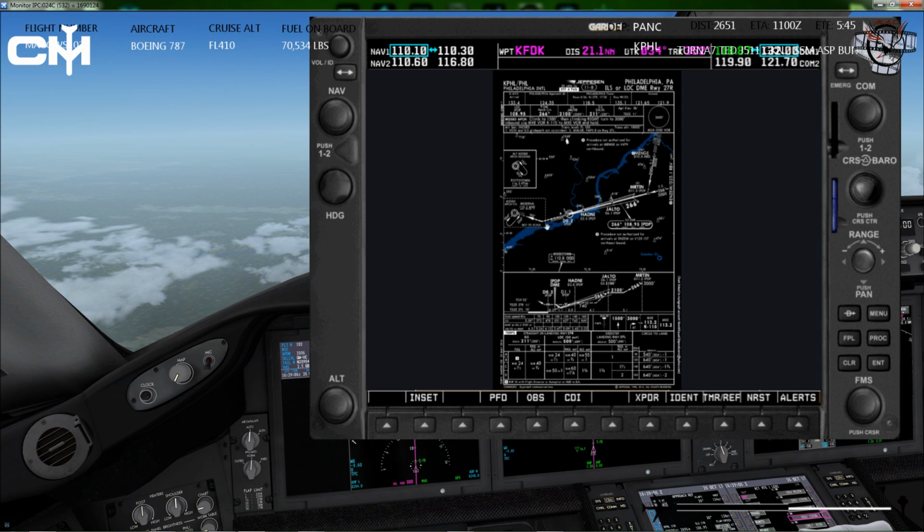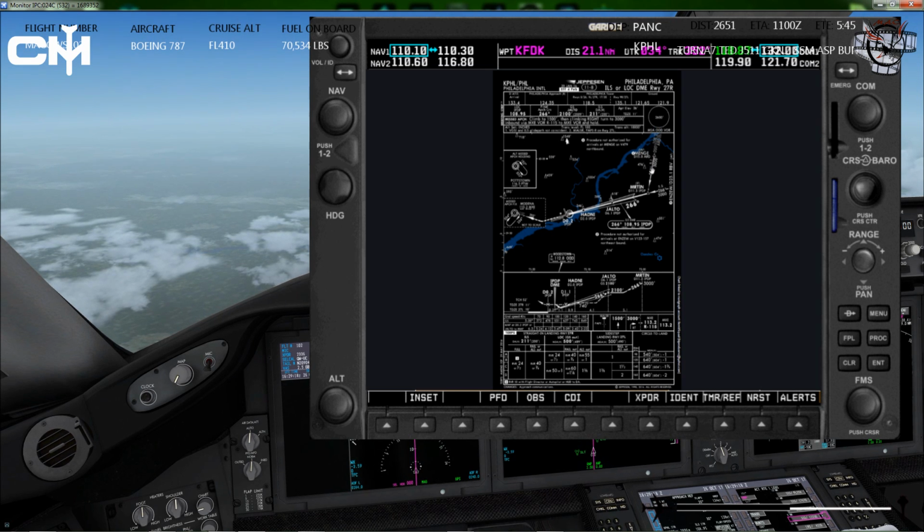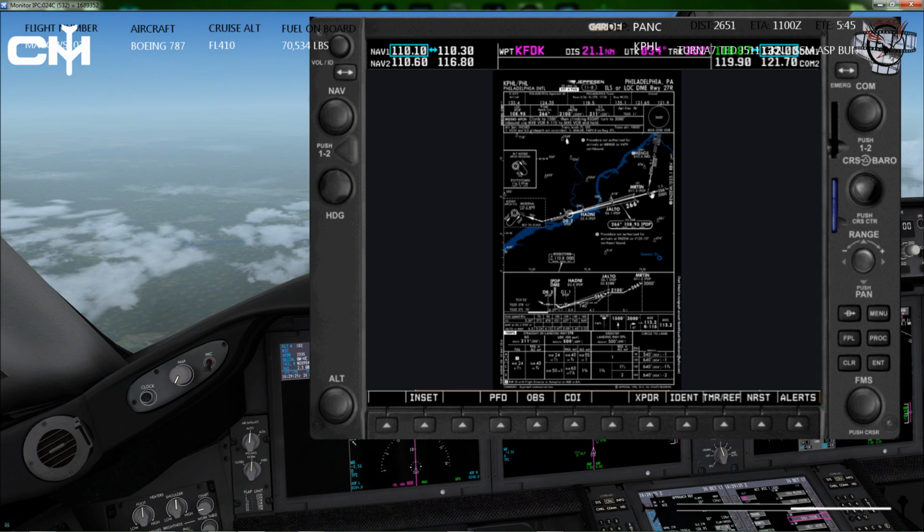Talk about the missed approach here in a minute, but let's take a look at our map view here. We're actually going to come in over here at Menge or Mengi, not really sure how we're going to pronounce that, but that's where we're going to come in at off of our arrival over here to Menge, and then we'll hang a right to 200 degrees down here to Martin. I think that's supposed to be Martin, and then a right on the final approach course from there of 266 degrees down to Jalto, then Hodney, and then on in from there.